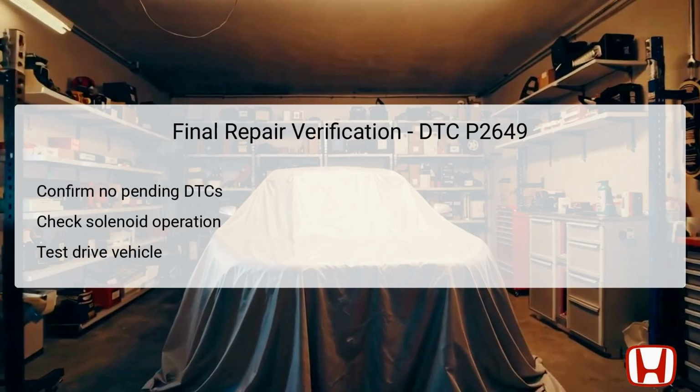For final repair verification, it is essential to confirm that no pending or confirmed DTCs exist once repairs have been made. After addressing the rocker arm oil control solenoid circuitry, ensure that the solenoid operates as intended. This may involve visually inspecting the solenoid while monitoring its function during an engine run test. Additionally, take the vehicle for a test drive under various conditions to guarantee that it performs without triggering DTC P2649 again. Effective verification ensures that all issues have been addressed, instilling confidence in the repairs made to restore normal function.